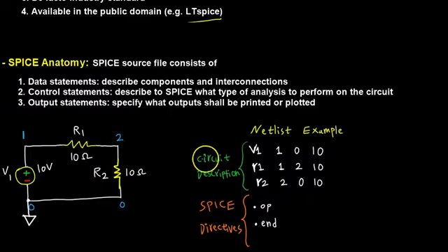across various nodes and through various components. So for example, if you have 10 volts here and you have 10 ohms and 10 ohms for two resistors in series here, you have what's called a voltage divider, and because these resistors are the same value, you're going to have half of the voltage source distributed across here. So you're going to have 5 volts here. So basically, by performing the operating point analysis, you're going to find the voltages everywhere. So you're going to see 10 volts here, 5 volts here, and 0 volts here. And then you can use that to calculate the currents through various elements.